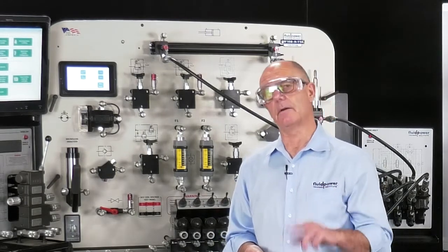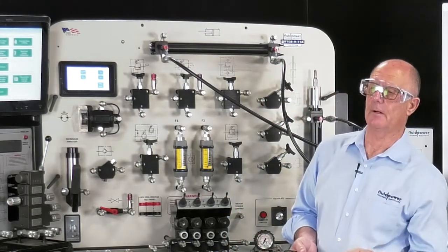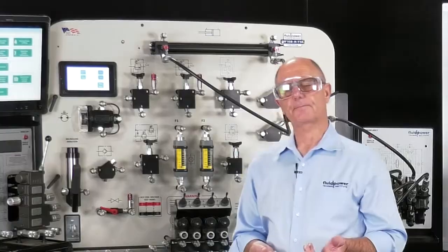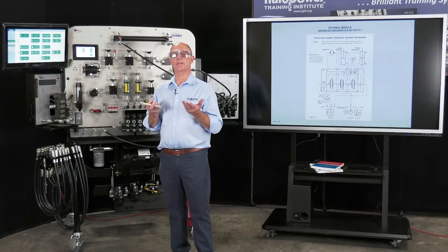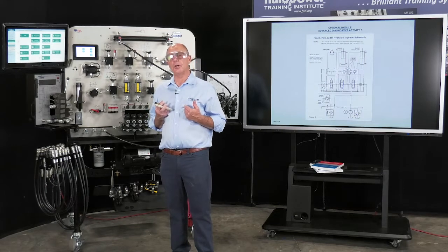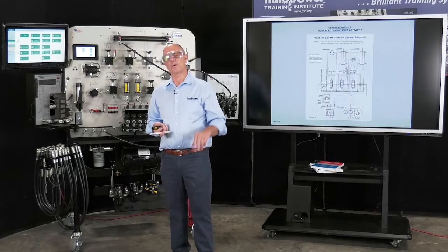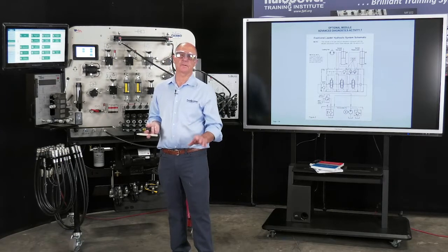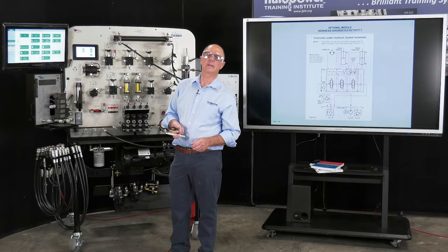Now let's go the other way. Let's say it's a two-stage Porta-Power that just produces a huge amount of flow, and let's say the valve is leaking. But I put enough volume into it where I can bring the pressure up. That's going to tell me a valve is good when it's actually bad. So anything to do with a Porta-Power is off the table as far as I'm concerned. And that's why I developed a pump that was unique to Microleak testing.